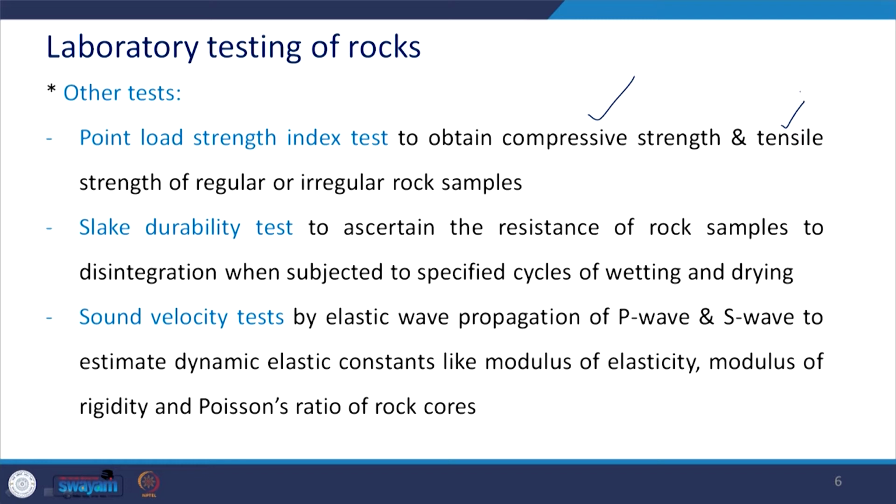Then the next test in this category is the slake durability test, which gives me an idea about the resistance of rock samples to disintegration when they are subjected to specified cycles of wetting and drying. There is a standard, let us say 2 cycles or 1 cycle of wetting and drying, and from there we try to obtain an index that is an indication of the resistance of the rock sample to weathering. So, this is what we do in slake durability tests.